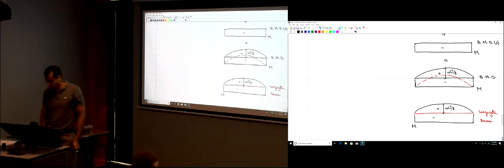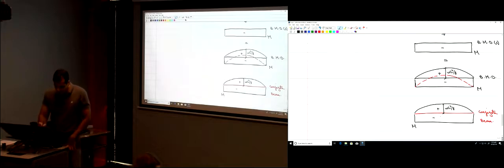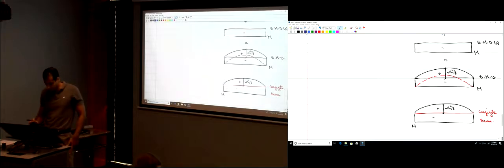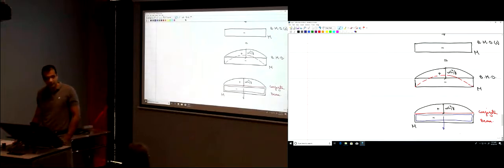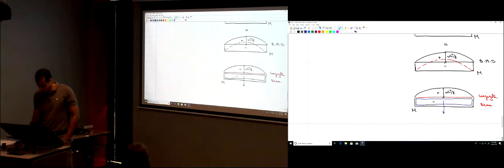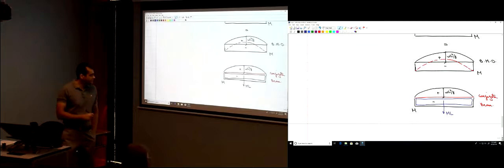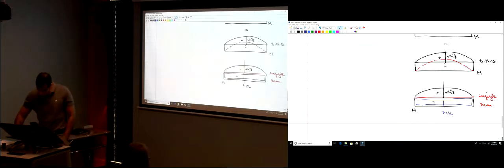Okay? So now this is a load applied on this beam. It's not the bending moment anymore. It's the load applied on the beam. So now I would like to find the concentration or the equivalent force of each of those loads. So for this uniformly distributed load, how much would that be? The area of that rectangle, ML, right? It's right in the middle. This parabola is symmetric as well, so its equivalent force is just right in the middle here, okay?